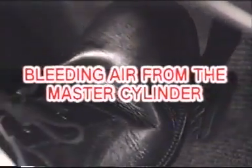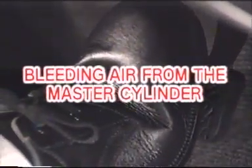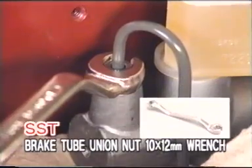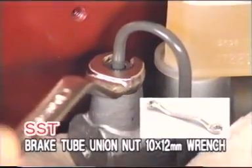First, bleed air from the master cylinder. Confirm that there is adequate fluid in the reservoir tank. Loosen the brake tube flared nut using the SST.